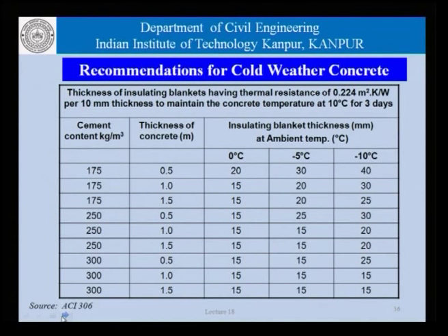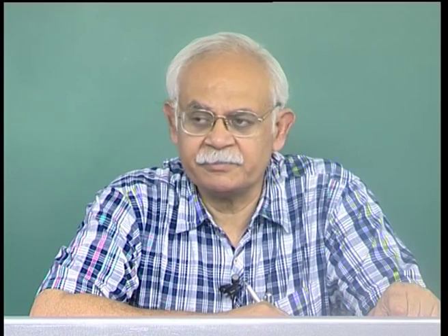This table here gives us a variation of the thickness of insulating blankets which may be required to maintain the concrete at a temperature of 10 degrees centigrade for 3 days. You would recall that we talked about maintaining a temperature of 10 degrees in order to ensure that the strength development or the hydration continues at an acceptable rate.